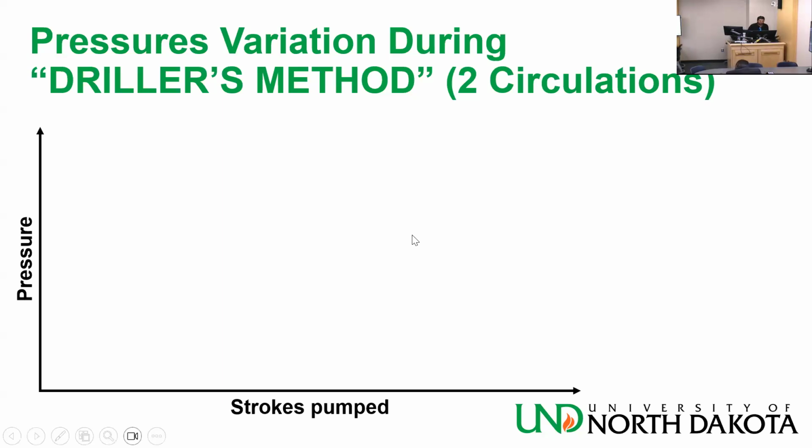Anyway, as I'm starting, I close the well. Okay, I got a kick, I close the well. I'm expecting the SIDPP to increase and stabilize here, right? If I'm lucky, and it's stabilized. You understand that part?